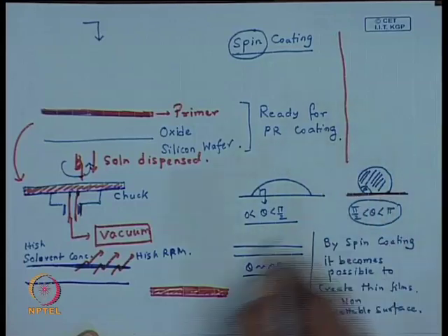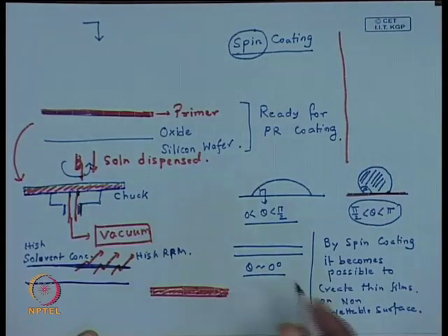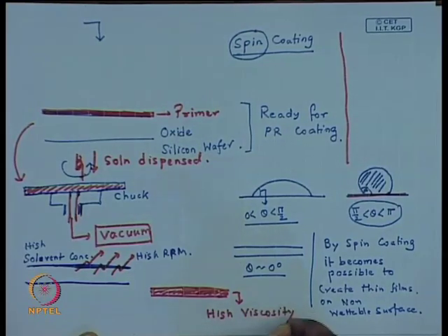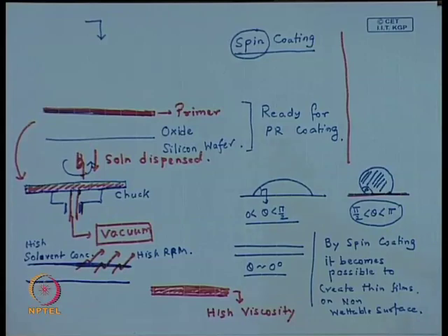but what now happens, these are long chain molecules and there is no solvent. So, they have extremely high viscosity. The molecules do not remain labile, they cannot move, because their mobility was essentially due to the presence of the solvent. So now you realize the importance of the solvent layer, which reduces the viscosity and allows the spreading of the photoresist or the polymer during the spin coating.